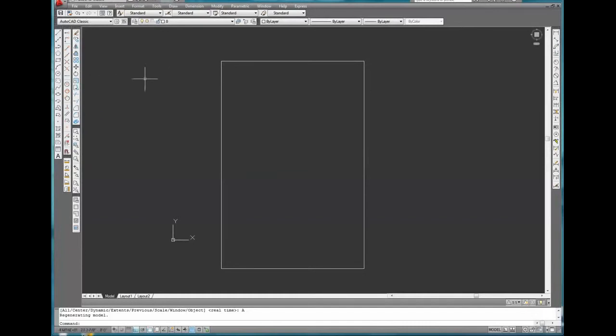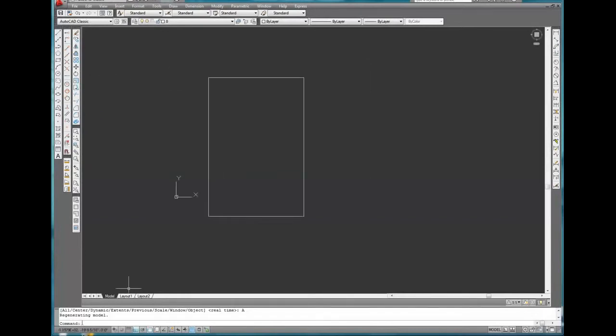And another way to draw a line is to enter the information into the command line. So let's say I click on the line and come over here to this point and click on the OSNAP icon there. Now I can type in the coordinates, and in order to do that, I'm going to have the at sign.